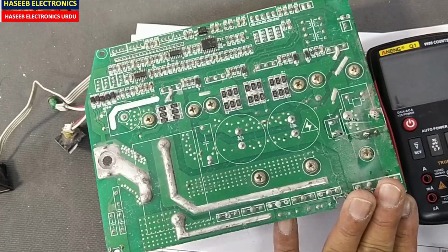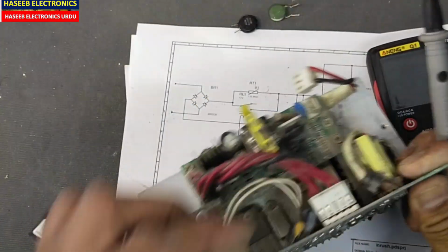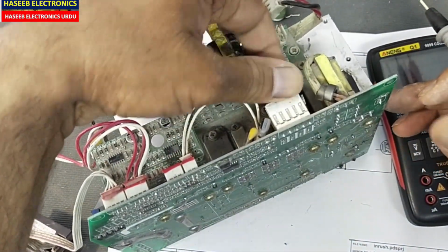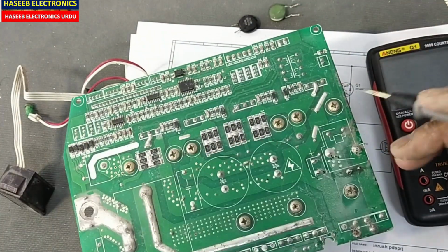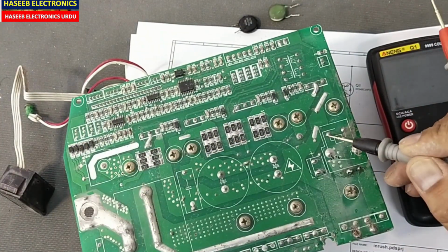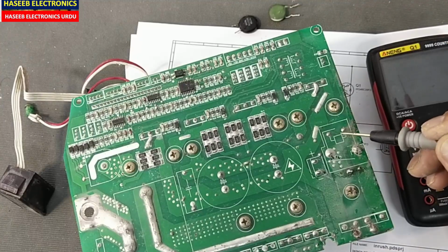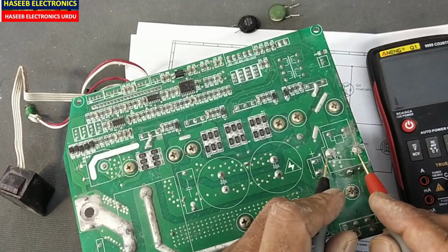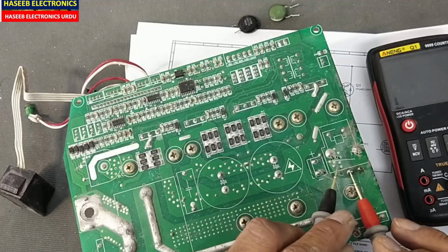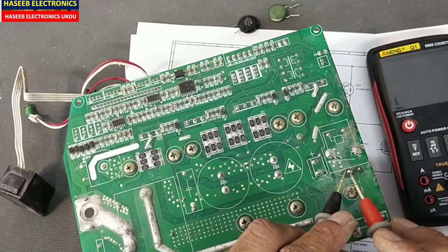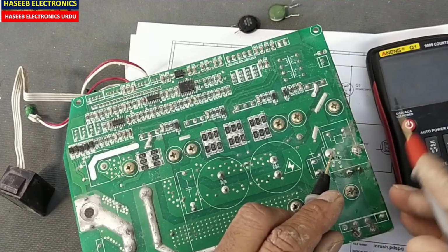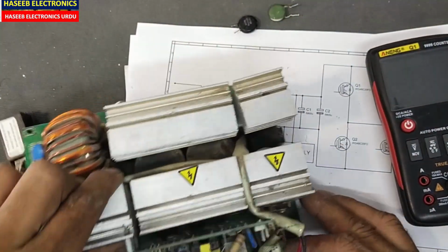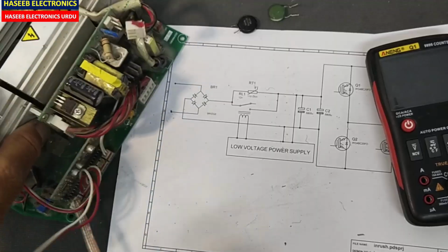Remove the machine from the power line. Remove this connector. How can we test the relay? Just remove this connector and apply 24 volt here at the winding of this relay. These 2 points, when you apply power here, must be closed. It will give continuity. In normal condition, it will give 100 ohm resistance, that is from this PTC. When it is powered on, it must give 0 ohm resistance. So these are the 3 possible causes for damaging this PTC.